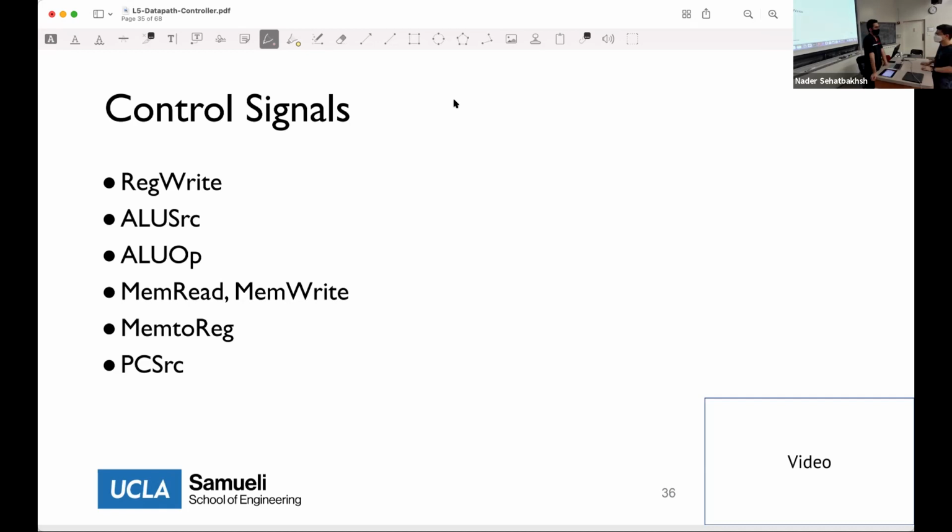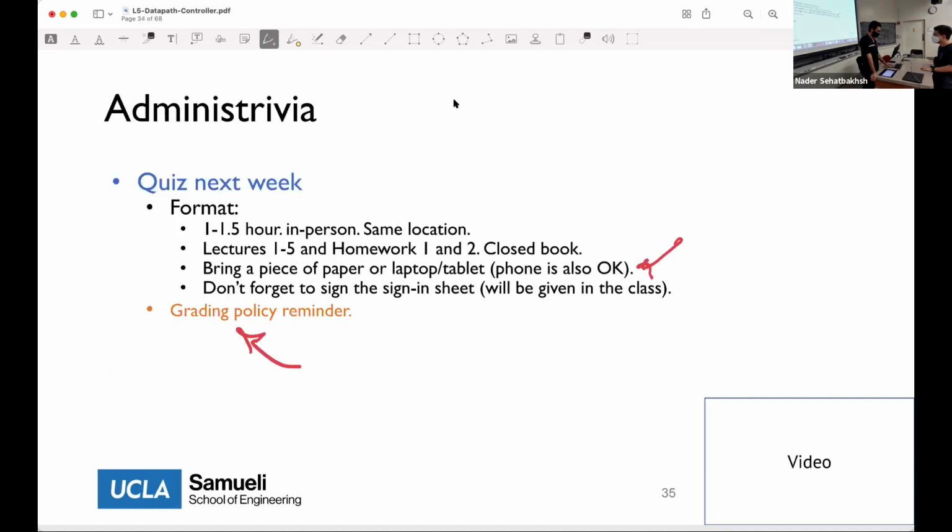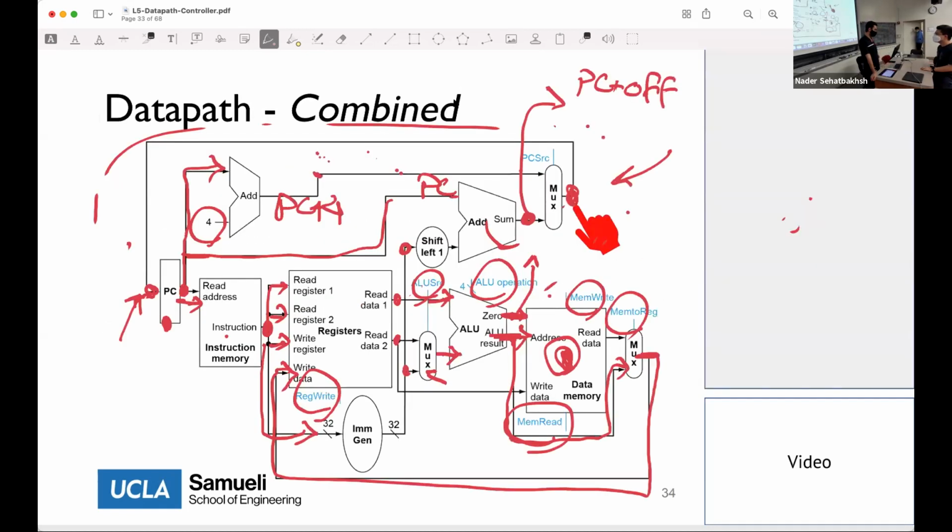It has, but you don't have any control over not clocking the rest of the design. There are ways of saving energy. First of all, flipping bits is actually where it consumes the energy. So if there are no bit flips inside the ALU, it doesn't really consume that much energy. On the other hand, most of these parts are going to be used anyway. The only part that may not be used is the memory, right?